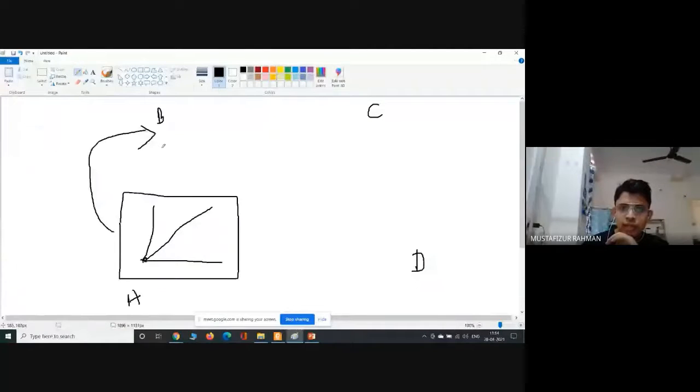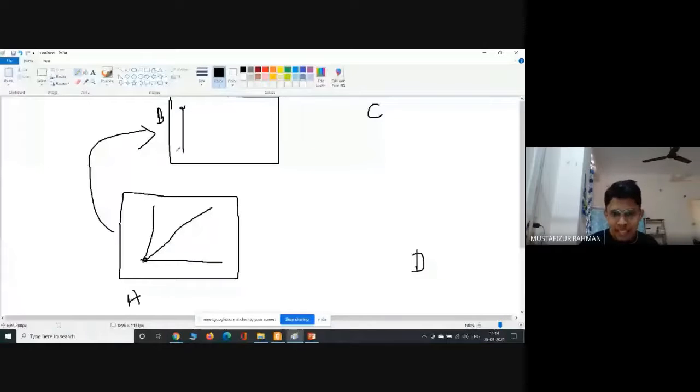At the B point, we have this plane table again. Then we already have B point. We will look back at A point. Again, we have to do backsighting. We have to look from B to A and make sure that the map line AB is perfectly matching with the ground line AB. Done. Then we have this point. Then we have this point.